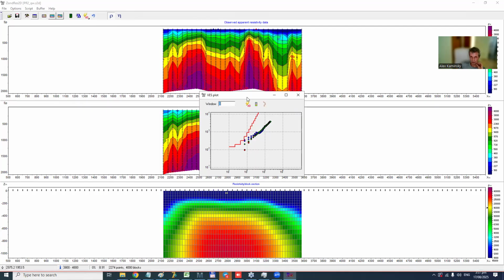So my idea was about, because usually we have the best data for shorter spacing because the signal is perfect. But I suppose that for such a highly resistive section, maybe there is a problem with overloading for the short-spacing signal, so big it couldn't be measured and it's reduced by some limit.